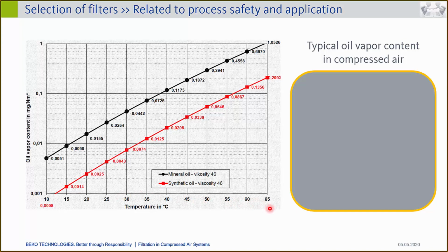But we also know that inside the compressor we have higher temperature, so the compression end temperature in degrees C is about 80 degrees. In worst conditions, if the compressor room has poor ventilation, it could easily go up to 100 degrees.